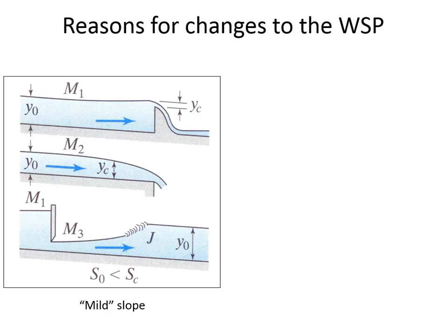And then here are some depictions of the hydraulic features that can cause these different types of profile. And we've talked about M1 plenty of times before, the types of things that could cause pooling and the water depth increasing. Here's that flow over the edge that causes an M2. And M3 might be where you've got supercritical flow. The depth is increasing even though the flow depth is less than both the normal and the critical depth.